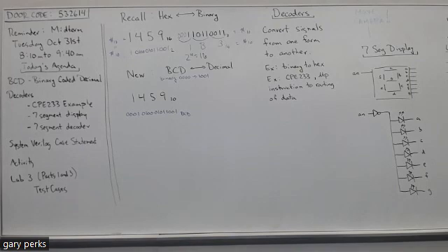And then under that is something called, or short for, interrupt, which doesn't really apply to what we're talking about here. But also, if you look up at the very top left, where there's a /7, it goes to IR and then in brackets 6 to 0. That's another 7 bits of the instruction register. The instructions in CP233 for the microprocessor you build is 32 bits. So this decoder is taking 7 bits, 6 to 0, then it's taking another 3 bits, 14 to 12, then it's taking a single bit, the 30th bit. And that's what's going on the input side.